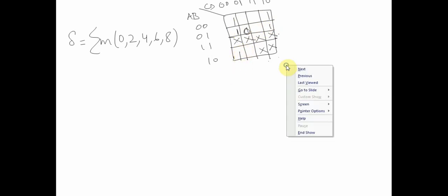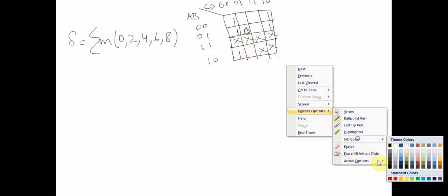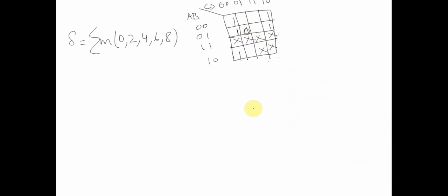And what kind of a combination is possible for this particular set of numbers? One possible combination is this 4 plus 4 8 blocks, right? So my delta would become equal to what is common in these blocks. AB is changing, CD only last D bar is common, right? So delta is equal to D bar.